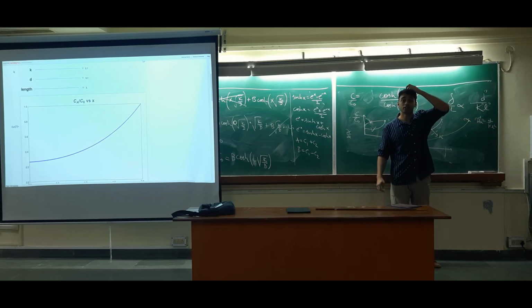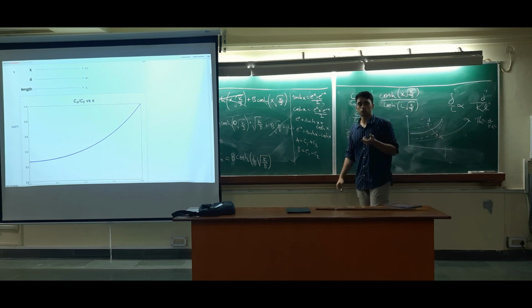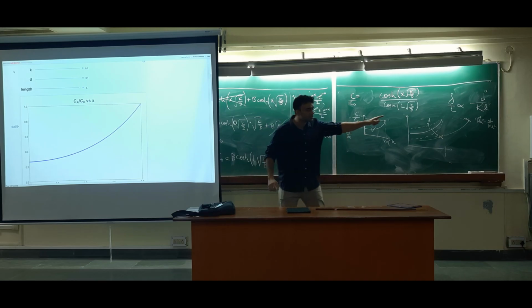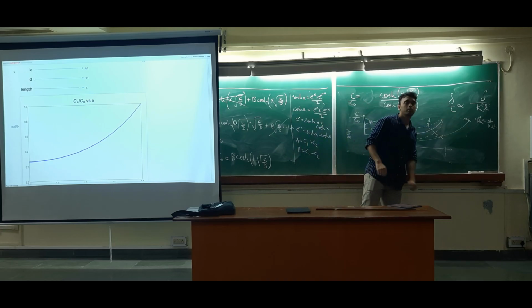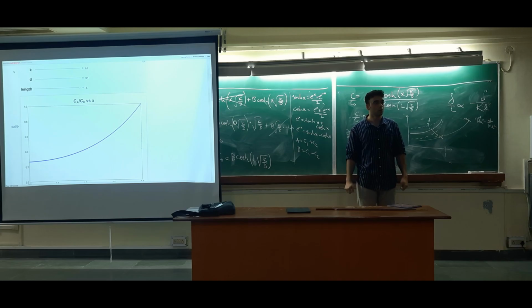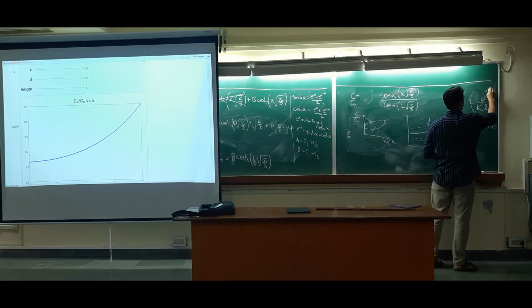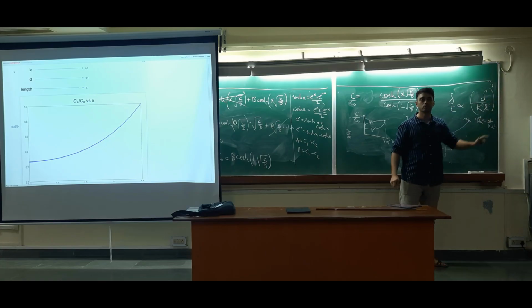But there is another disadvantage of dimensional analysis: it cannot tell you with what exponent it will depend, -1, -3, +1, +2, half, 1 by 3. We covered this, right? So you can still do dimensional analysis and make it compact, and say that this non-dimensional number will emerge and my answer will depend on just the Damkohler number. But you still have to do numerical simulations to find that power. You can find relative powers, but that overall power will only be revealed from the simulations.